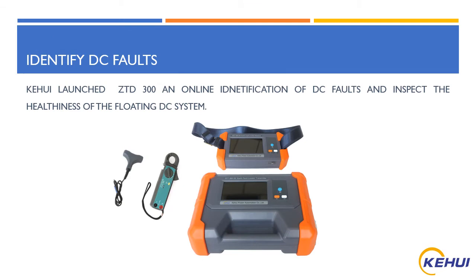The conventional method is to switch off and switch on each feeder to see whether the system is getting stabilized or not, which also helps to identify which feeder is faulty. In that case, if the wrong feeder is switched off, it can create a lot of damage to the asset or other electrical failures in the system. To avoid such cases, we have launched a new online DC earth fault identification system.